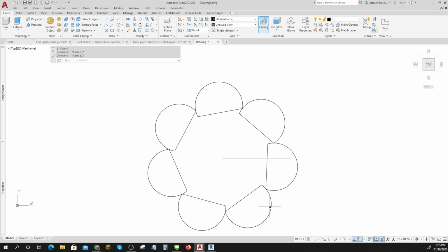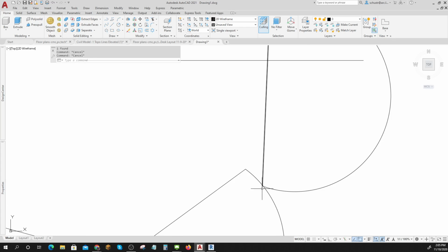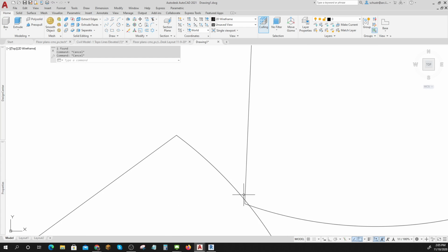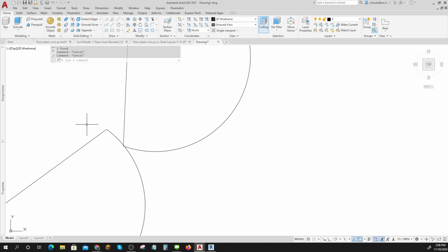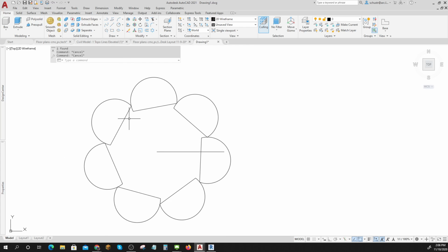To do the press pull, so it's going to be one of those two things. You either need to explode it, or you've got some sort of little overlap or gap where it doesn't think it's seeing all one thing. Okay? So give that a try really quick and see if exploding it works or if you can find one of the little things. And then for the angle on the tooling brace,